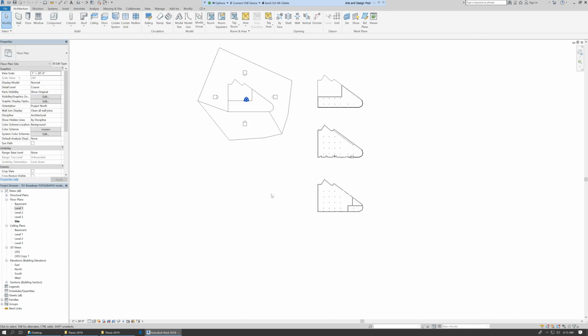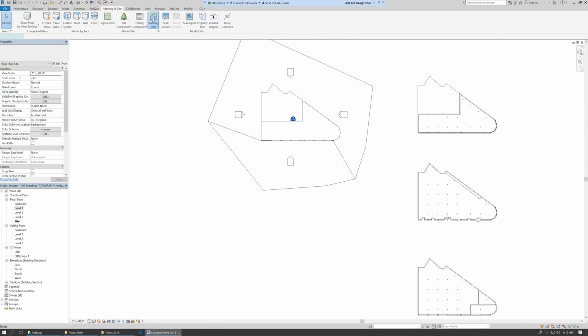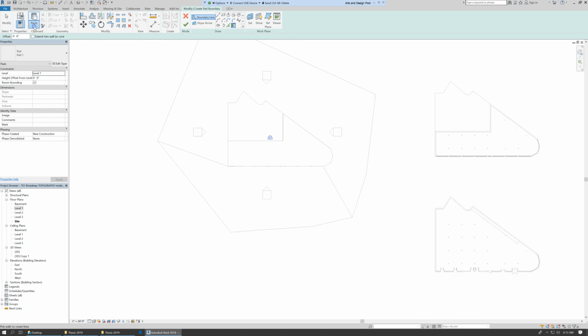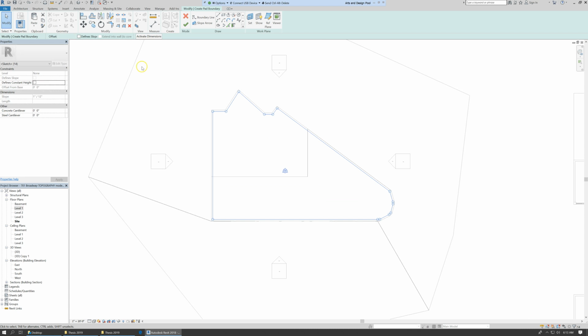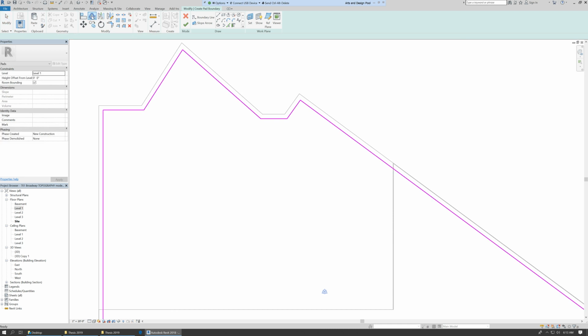So I'm still in the site plan, but now instead of drawing the floor, I'm going to go into massing in site, draw a building pad. So it brings me back into sketch edit mode. I just paste from the clipboard aligned to the current view, and then I'm going to select the offset tool to move these lines to the outside, uncheck copy, and we want to move them in that direction, this way.